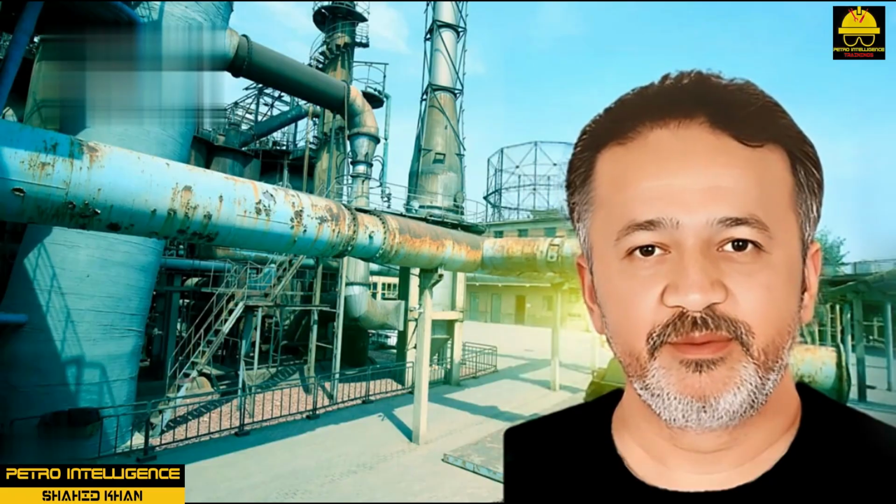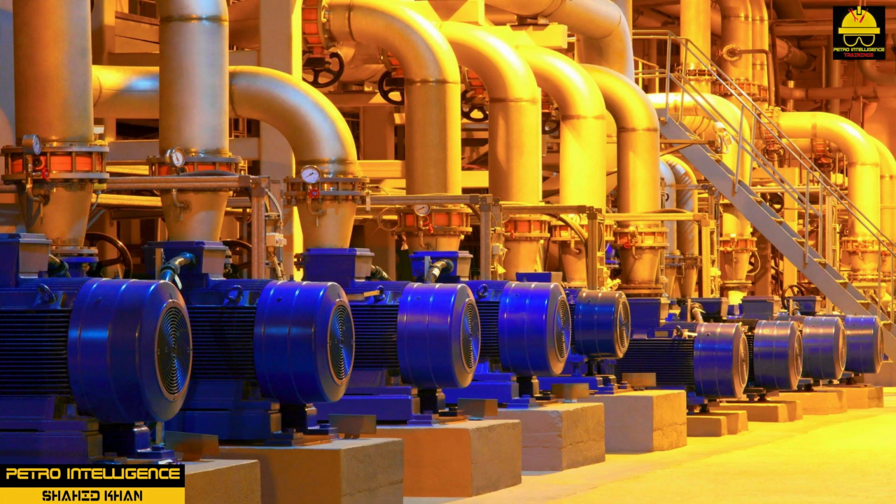Motors. Most of the motors in the plant are the 3-phase induction type. Each of the pairs of poles is wound with one of the phases of the AC supply. The effect of this winding is to produce a rotating magnetic field. This field, in effect, pulls the rotor behind it, thus imparting mechanical energy to the machine. The induction motor always rotates slightly slower than the magnetic field.